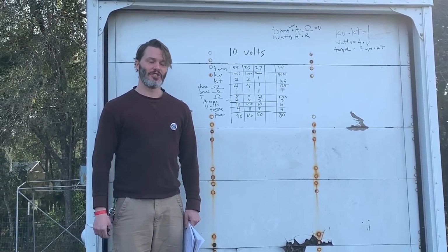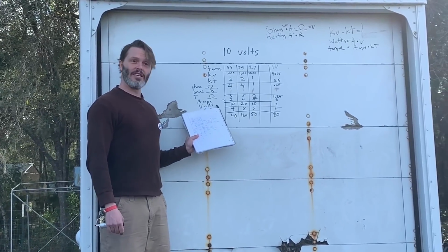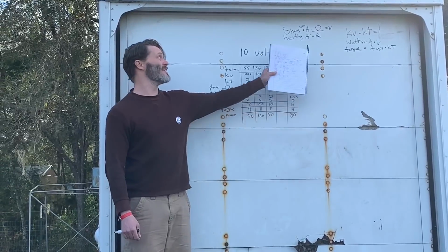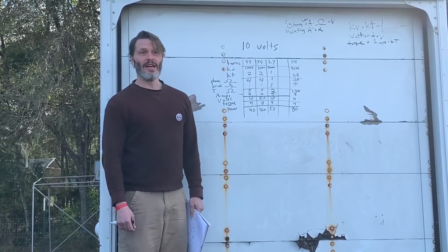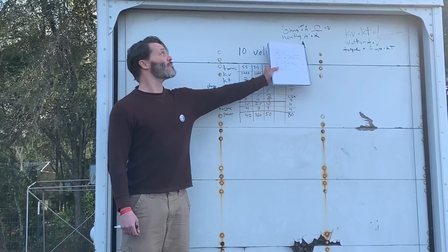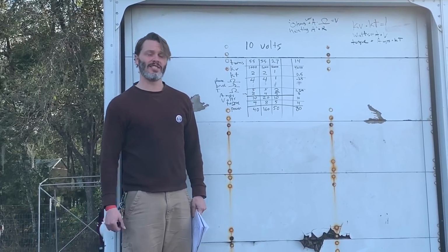I wouldn't ever suggest gearing up, of course, because when you gear up, you actually end up having more phase amps on the motor. You have more heating in the motor. You have more need for your ESC. You have more heating in there. And let's say you doubled your gearing on your rig, you have twice the amps, but since the heating is the square of the amps, your heating just went up 4 times in your ESC on the phase side.